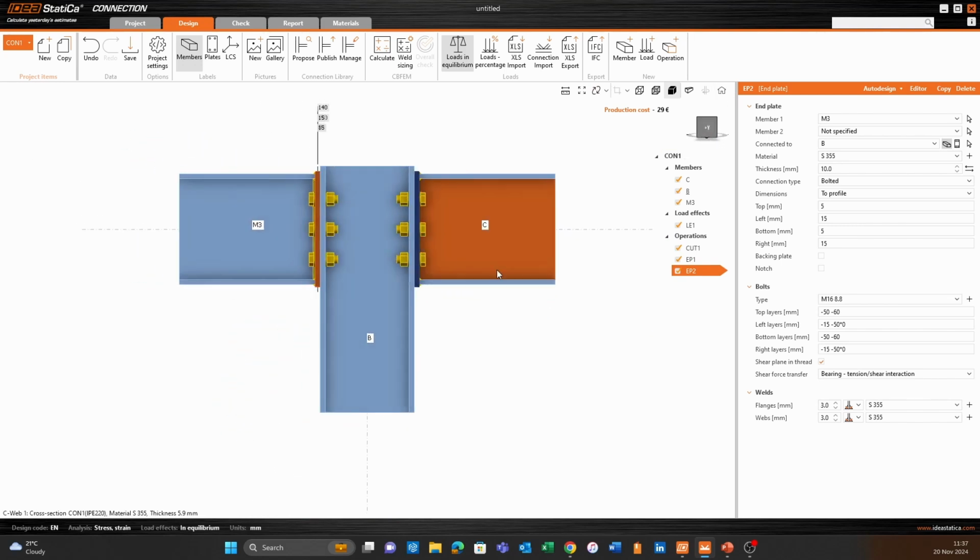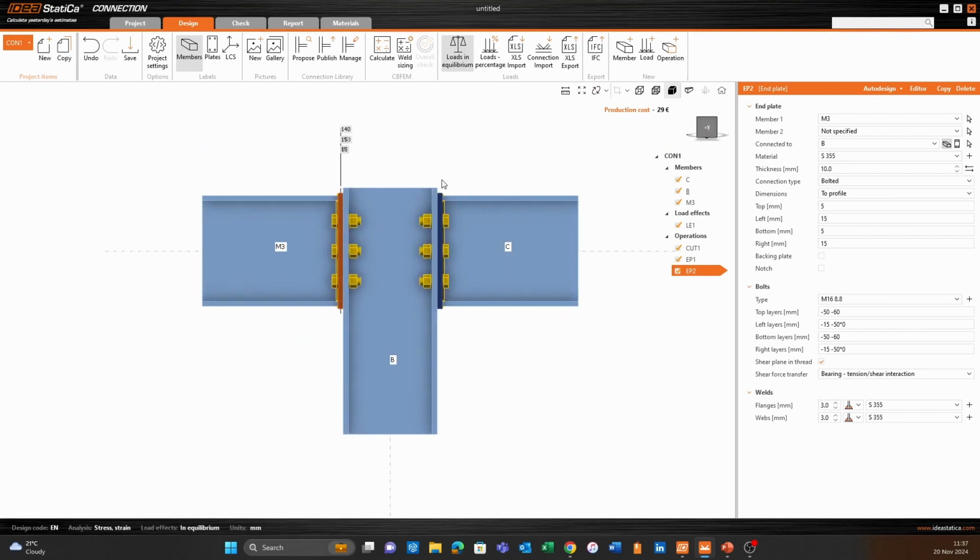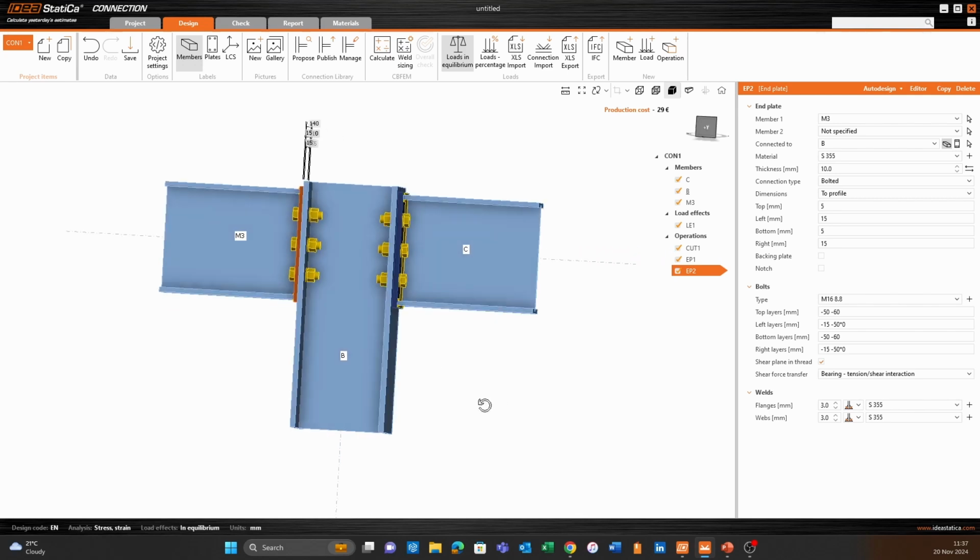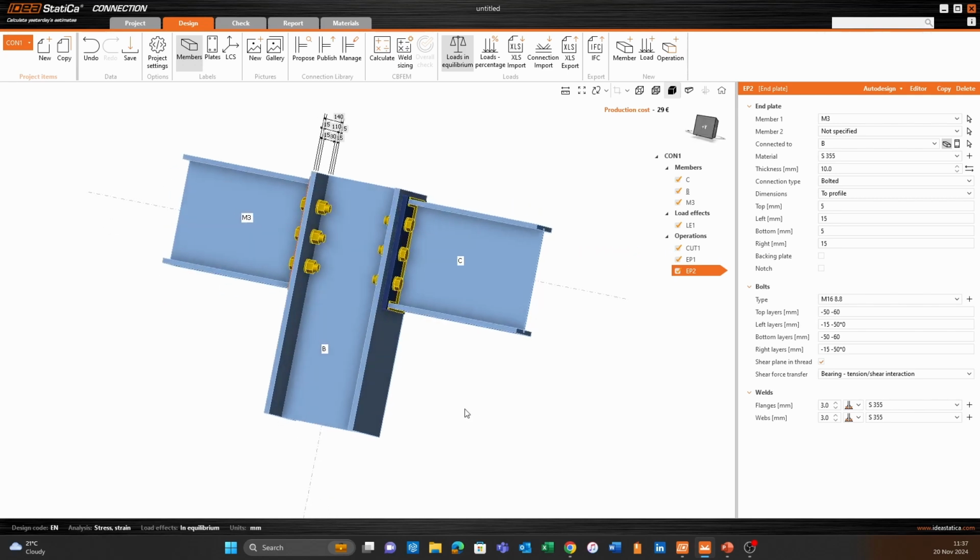Now, the temptation would be, especially if you're using Checkbot, to physically go and extend the column in the actual FEA or analysis model. In general, with analysis, we model on shear centers. So how this connection was initially presented to us is what it will look like in the analysis package as well. But we know that in reality, this column will extend slightly above the connecting beams so that you can connect into the end plates. Otherwise, you'd splice the two beams together and then have an end plate connecting to the bottom flange of the two beams. I hope that really helps.